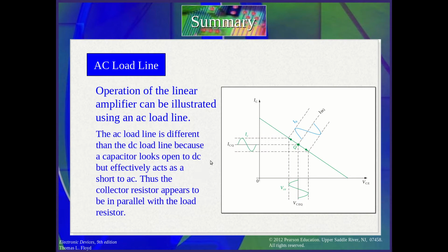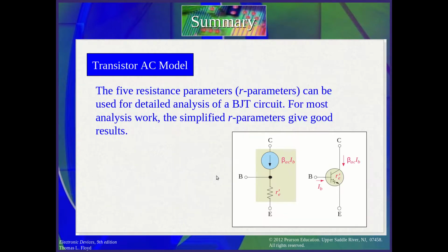So here that's what I say. Transistor AC model. The model here for the AC sees a small resistance inside the circuit, or an equivalent inside the transistor, an equivalent circuit. So we name it the r parameters. We have to take into account or calculate all the resistance inside or around the circuit, so you make it an equivalent model. As you see, a source of voltage or current and a total resistance of the circuit. So this is the base, emitter, collector.